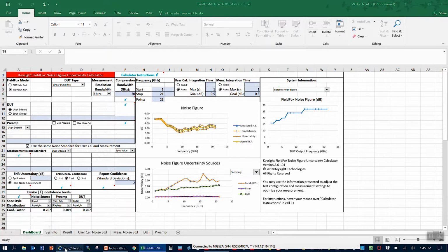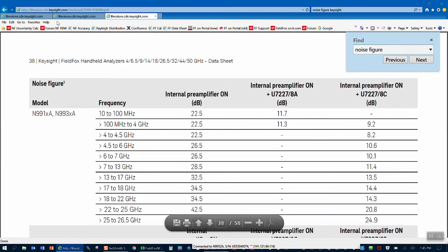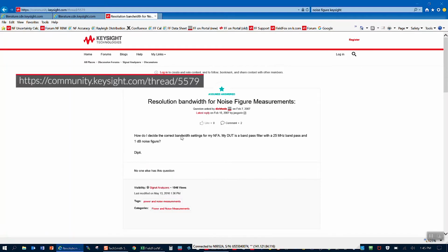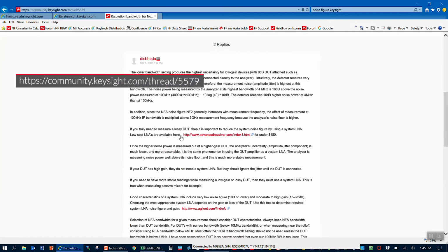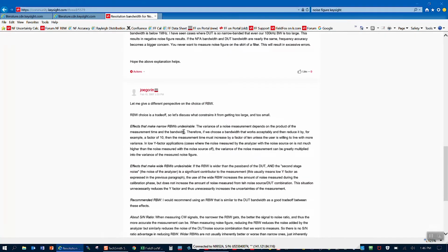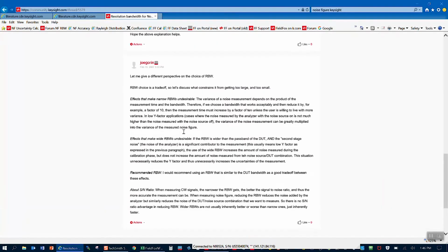If you want to read a detailed explanation of this, there's a great discussion on the Keysight forum, and you can see the URL on the web. The first part is somebody answering the question of res bandwidth selection with an intuitive explanation. The next person who's answered is Joe Gorin. He's our noise figure expert and co-author on some of our app notes here. So you can read a more technical explanation of how you select a res bandwidth, and he recommends using a res bandwidth that's similar to the DUT bandwidth as a good trade-off.